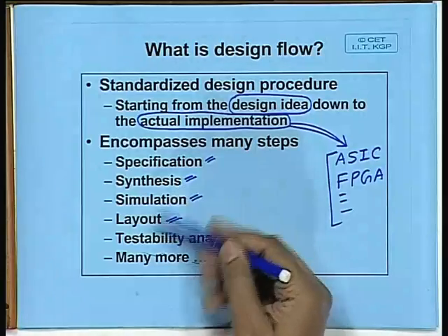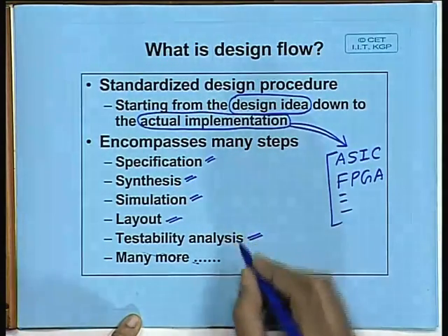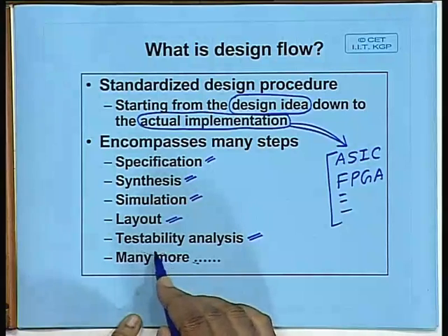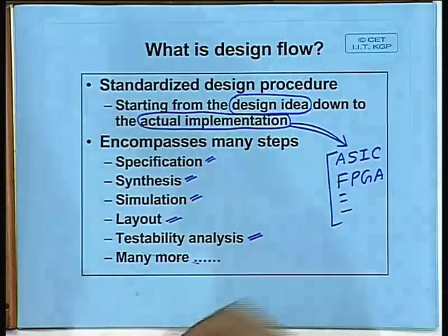Now, during synthesis and layout itself, you often also consider some issues related to testability. This means when you are designing the circuit, whether the circuit is functionally working correctly or not is one issue. The design being correct or not, that of course is a very big issue. But after manufacturing there can be a number of defects. There can be some short circuit in the wires, there can be open circuits, there can be a lot of other problems in the transistors. So, after manufacturing you have to test the chips.